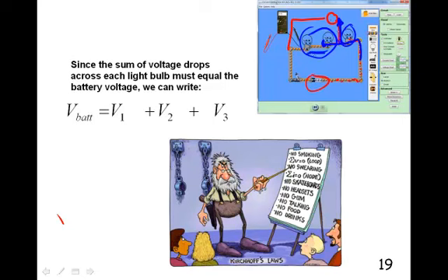That's one of Kirchhoff's laws that says the sum of the currents at a node is 0. And an easier way to state that: a node is a place where the current can branch off. What he's saying is that the current that goes in there equals the current that goes out. So here we've got some current coming in, some comes out here, some comes out there. So if this was 3 amps and this was 2, guess how much this one would be? 1. All right, that's all that Kirchhoff's current rule says.